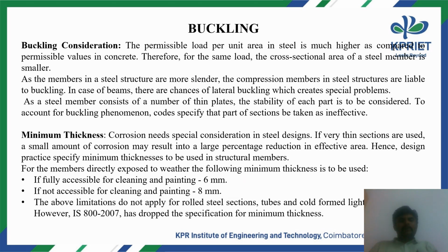And then buckling, what is buckling? First one is buckling considerations. The permissible load per unit area in steel is much higher compared to the permissible values in concrete. Therefore, for the same load, the cross-sectional area of a steel member is smaller. As the members in steel structures are more slender, slender means a long member, without any braces.